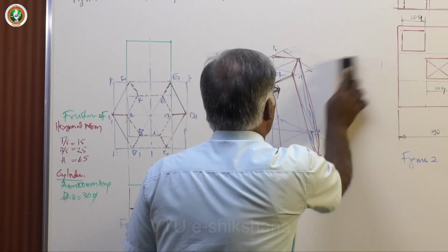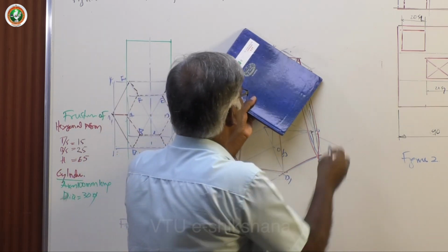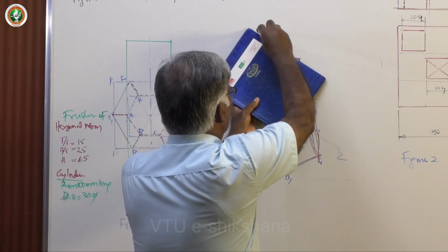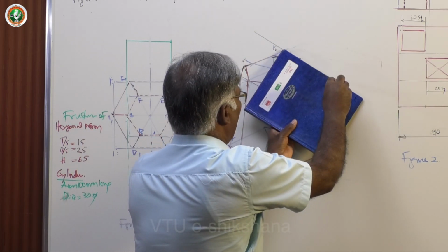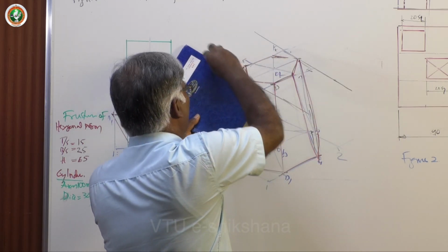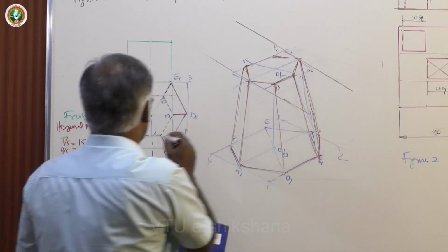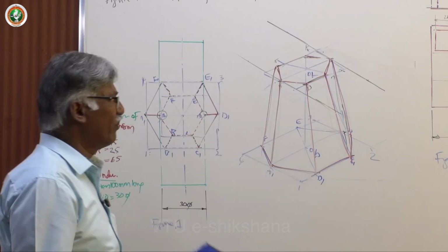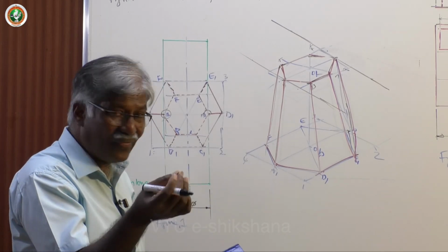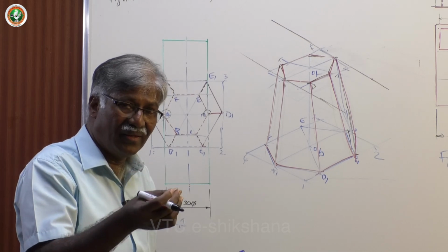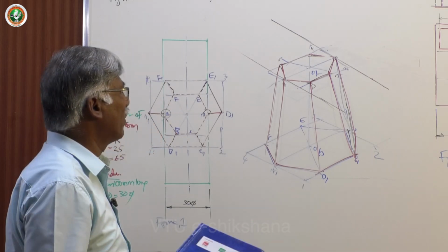Now let me draw 30-degree lines through these corners. I am creating one of the lateral surfaces, that is a rectangular face, passing through these corners, because it's easy for me. In the computer, what you do is separately create the cylinder, then identify the lowest point line which is going to touch the surface and keep the midpoint of it exactly here. I will show you on the computer how to do it.